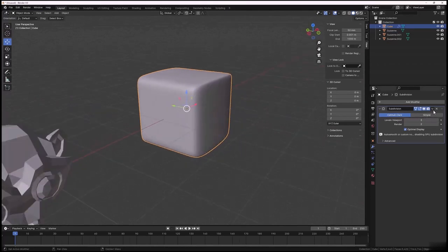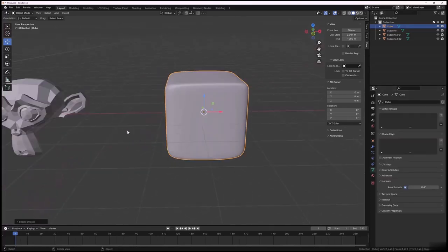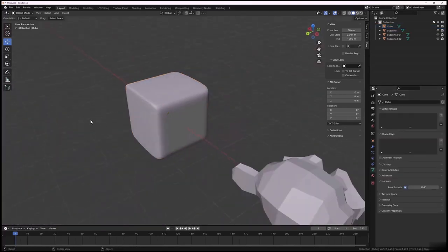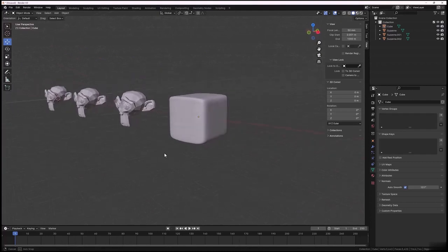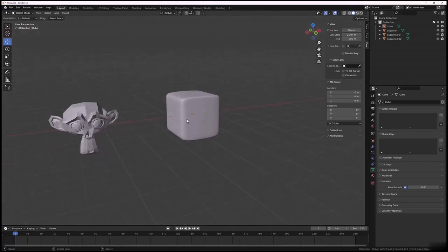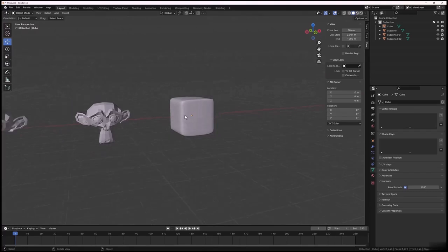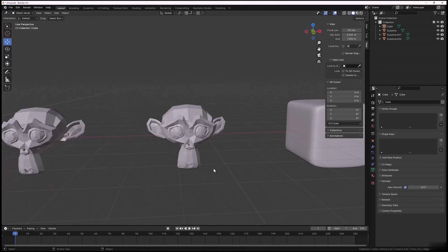Let's go ahead and apply that. So hit that button there and press the apply button. So we're going to apply the subdivision surface modifier. There we go. And let's soften the edges slightly more. So you can see now how we can actually use the subdivision surface modifier to our advantage to soften all the edges, create new shapes, but still have some say on what actually happens. So let's see what we can do with Susan now using the subdivision surface modifier.